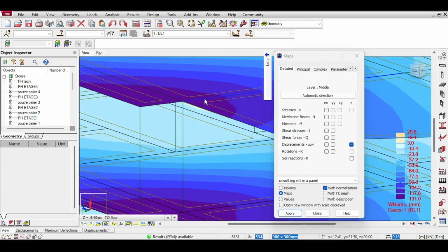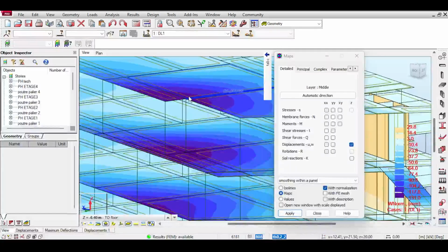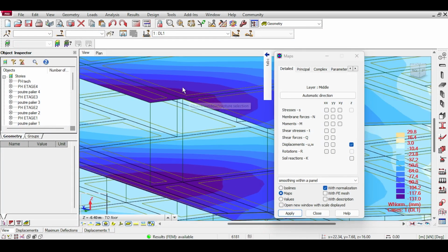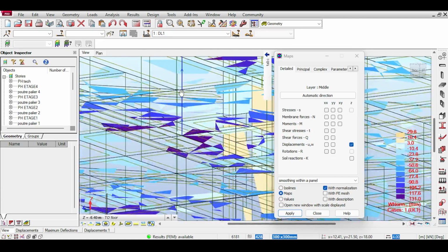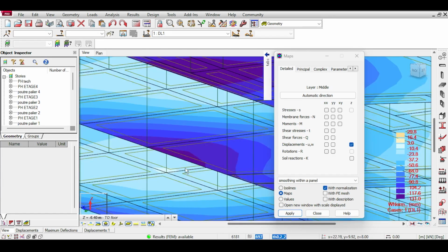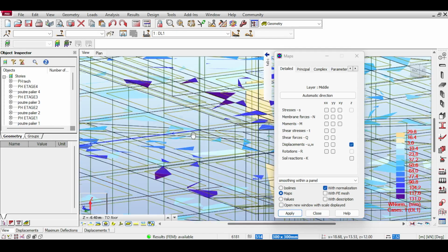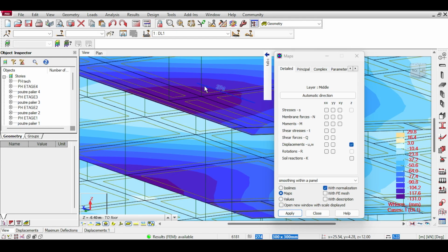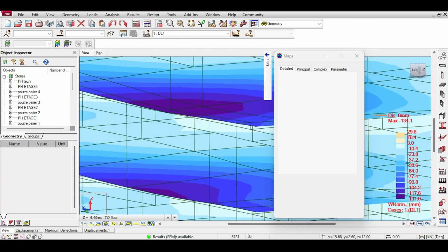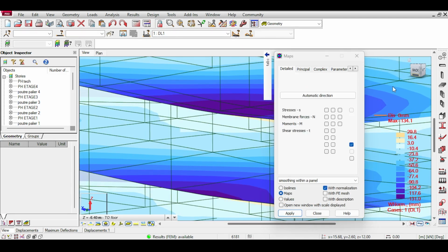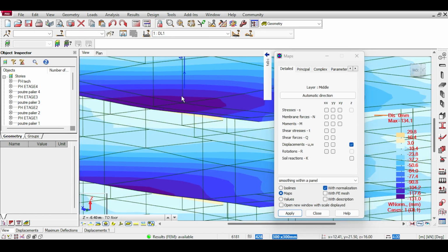Now, this shouldn't deflect because there is a column. However, look, this is how we study deflection. You follow something called the load path. This shouldn't deflect that much because there is a column. Now, if it deflects that much, then the column has deflected. And you can see that the column continues deflecting until here. Here, there isn't much deflection. So there is something that happened to the load path, and I am thinking the column is discontinued. So let's take a look. So is that the case? Yes, that is the case. The column has been discontinued. But why?